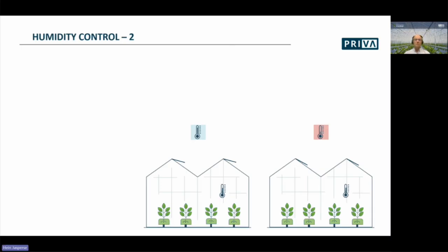The reason why it is possible to adjust minimum vents because of the outside temperature is also agreed by Plant Empowerment. When it is cold outside, the humidity can be controlled due to condensation on the glass. And in that situation, there's no need for a minimum vent to get rid of humidity. But when it's warmer outside, humidity control needs a larger minimum vent position.